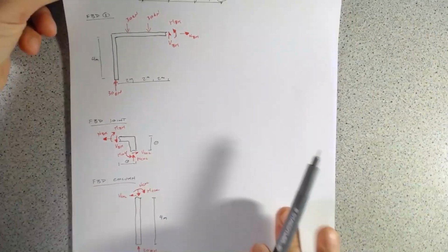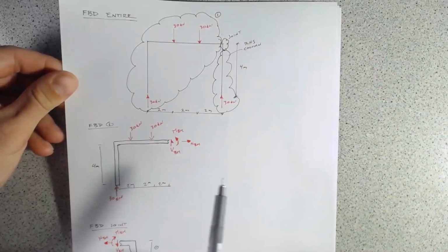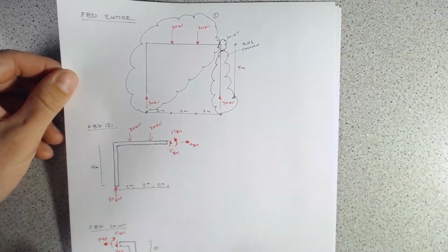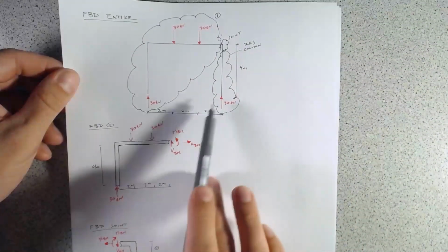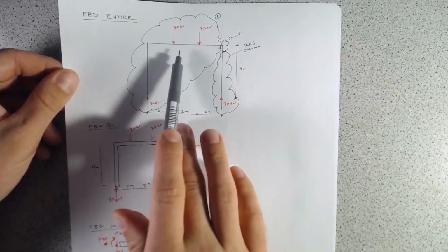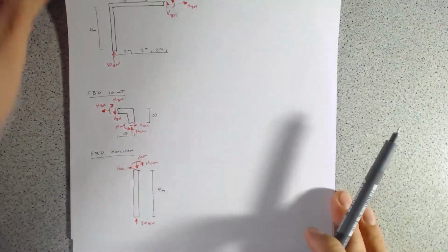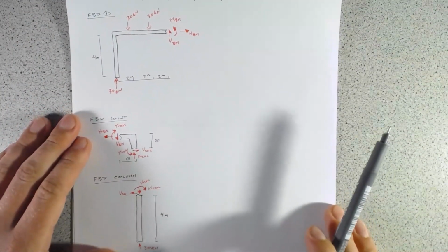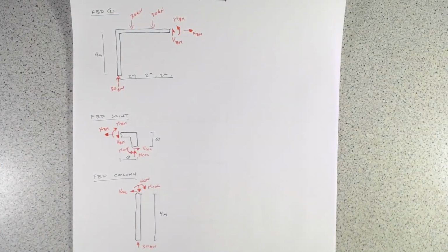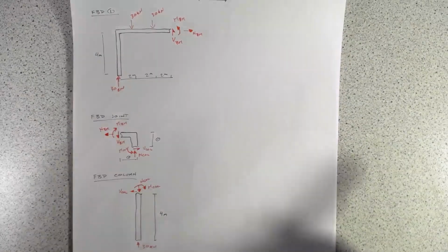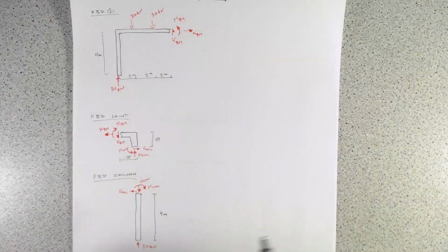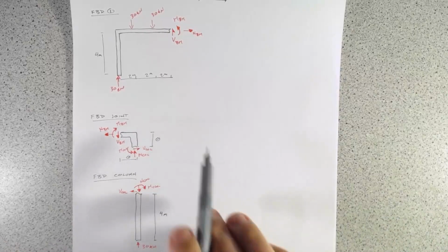Another note is, because we have a symmetric system, I'm only going to be looking at 1/2. If we had asymmetric loading and the like, we could do the same process and then just take another series of cuts. So in order to find out what these internal actions are, and then by those internal actions find out the magnitude of the shear force or the bending moment diagram, and then be able to draw our bending moment diagrams and shear force diagrams and axial force diagrams, let's start doing some statics.